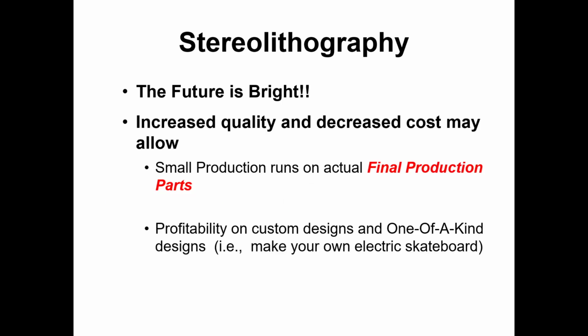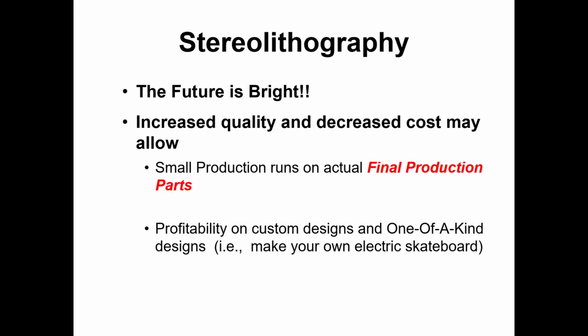So stereolithography is very important, but you have to keep in mind that it all comes down to the quantity that you're trying to make, because the fastest stereolithography machines are still pretty slow. If you want to make thousands or millions of things, which is what humans do, you need to have automated machinery that does this. And stereolithography is just too slow. You're not going to be able to make thousands and millions of parts.